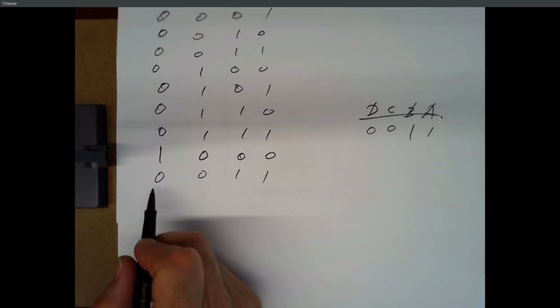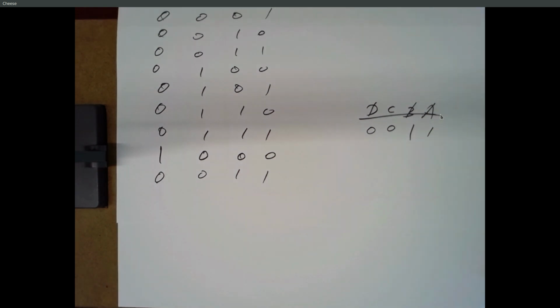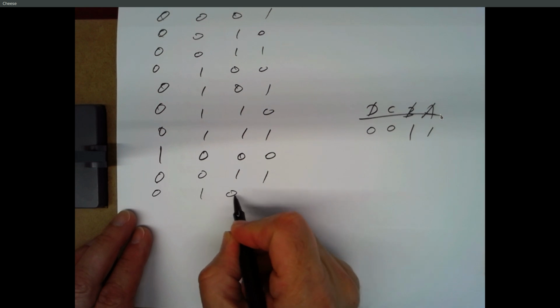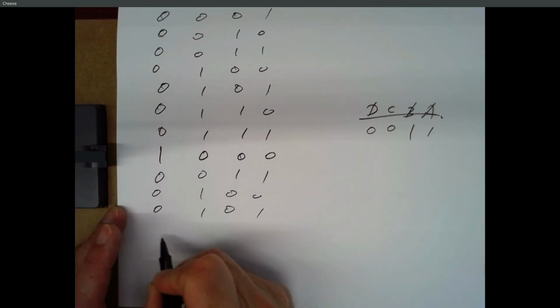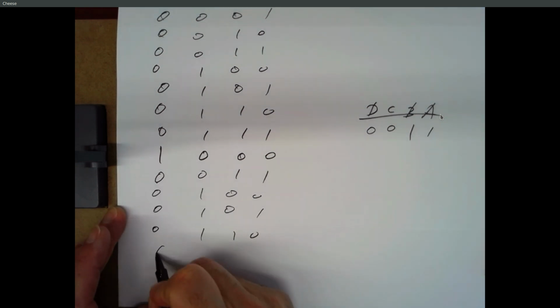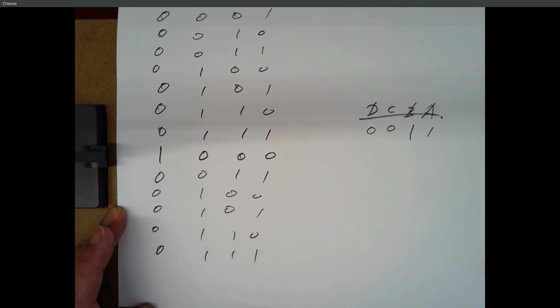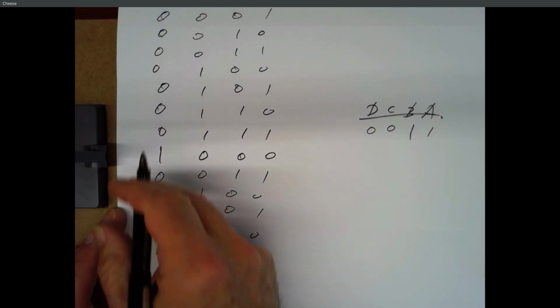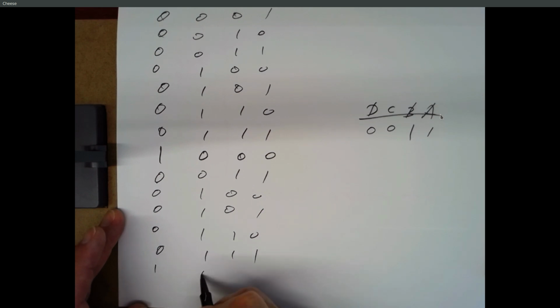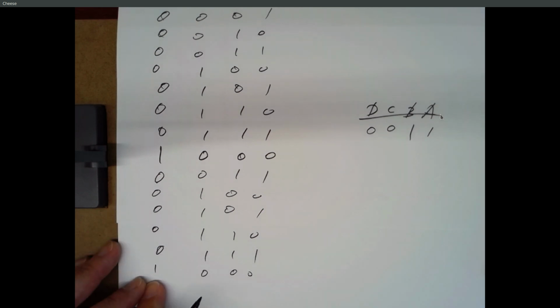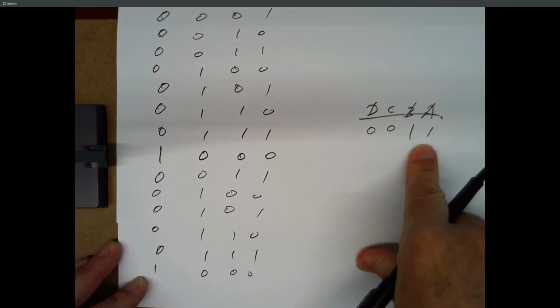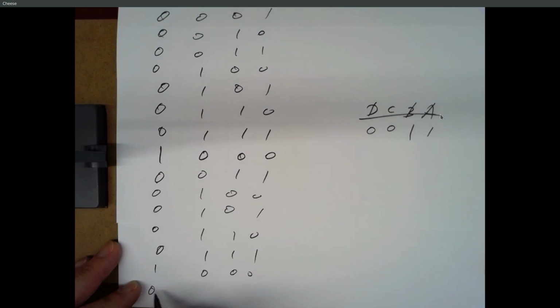And now, since QD is a 0, that comes around, the load input is a 0 again. So now it's just going to count normally. So the next time, it'll go to 4, and then 5, and then 6, and then 7, and then we're back in the situation we were in before. 7 will get incremented to 8, but now the load line is high. It's getting ready to load into 3. The next time the clock ticks, it goes back to 3, and that pattern just repeats.